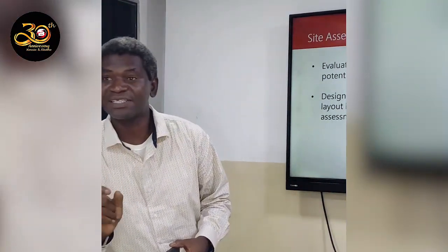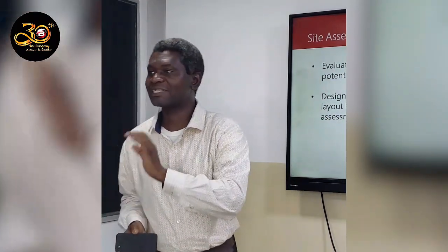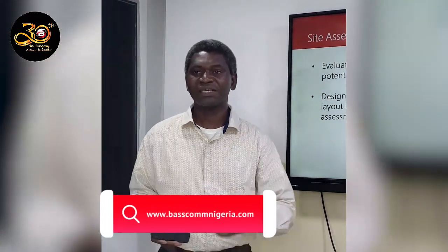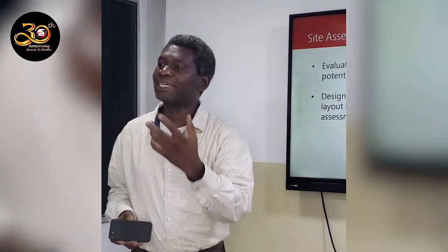Now, the second point I'm going to quickly mention is the site layout. This is where you do it. When you get to the site and you are doing an assessment, you should have a sketch of this is where the panels will be, this is where my breaker will be, this is where my batteries will be, this is where the inverter will be. So in our site assessment reports going forward, we should have sketches of whatever site we go to visit. And those sketches, you will have engaged with the client.